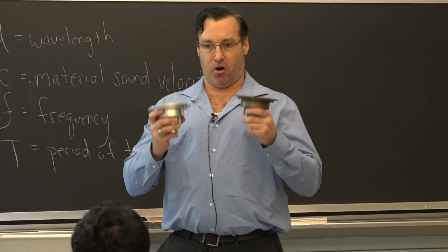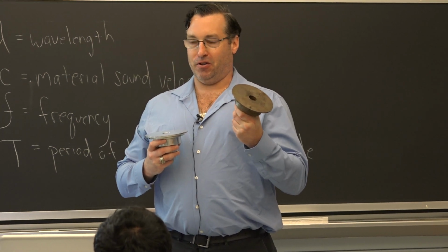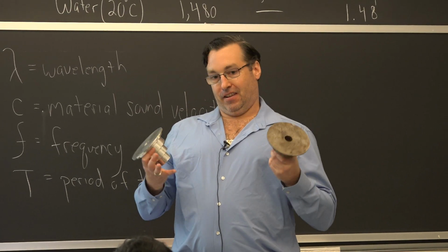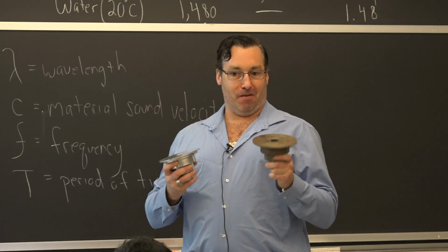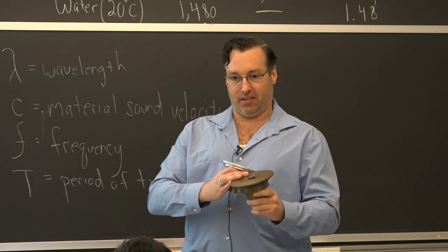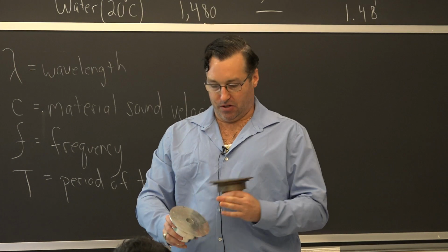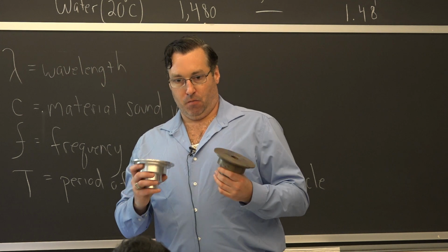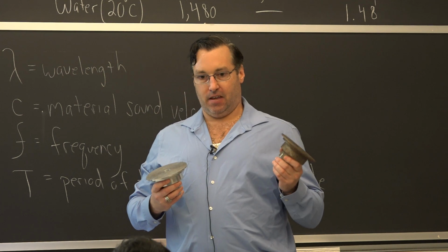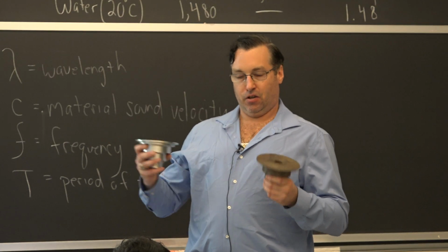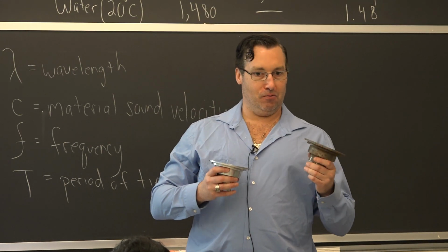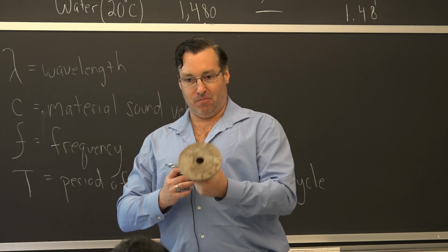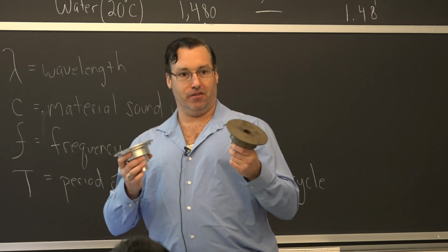The other thing that is important is that it is material specific. When you're doing an immersion technique, you have to make sure the material won't be corrosive to the water. This was a mild steel, 8620 steel. You see the difference for an aerospace application. That's why it would be critical to know if any of those alloys in that engine could corrode. Even though you can do the inspection underwater in an immersion technique, sometimes you would have to sacrifice the entire part to do the inspection.